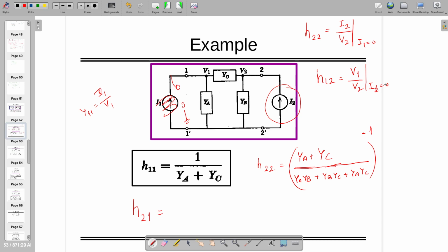I'm asking you because we have solved a similar thing. You will encounter only two kinds of circuit: either T type or Pi type. Y parameter is good for pi generally, and Z parameter is good for T. So it's up to you.